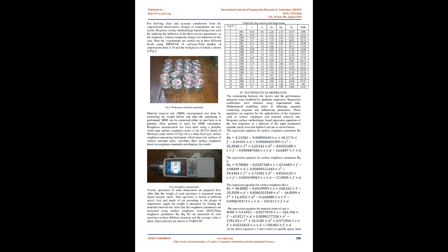[14] carried out optimization of 2 different grades of nitrogen alloyed duplex stainless steel by using Taguchi method. Machining was performed using TiC and TiCN coated carbide cutting tool inserts. Surface roughness, cutting force, and tool wear were taken as the responses. Variation of these responses with respect to cutting speed and feed rate were studied at constant depth of cut by using signal-to-noise ratio and analysis of variance.